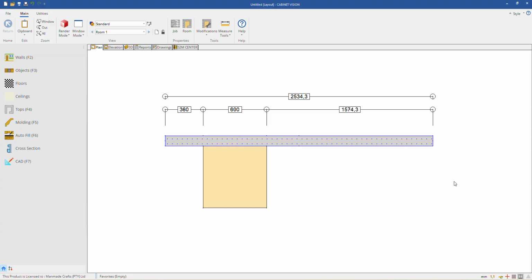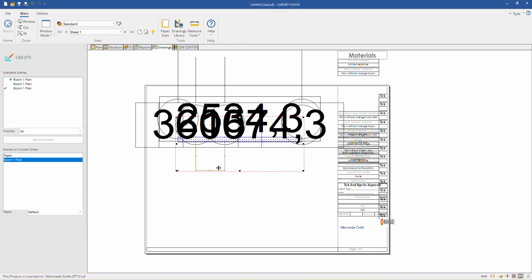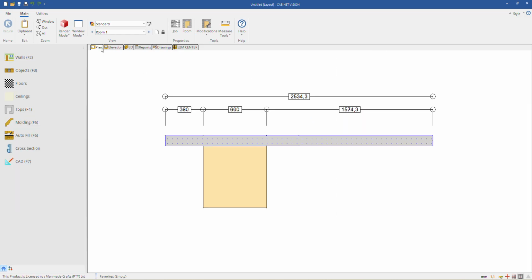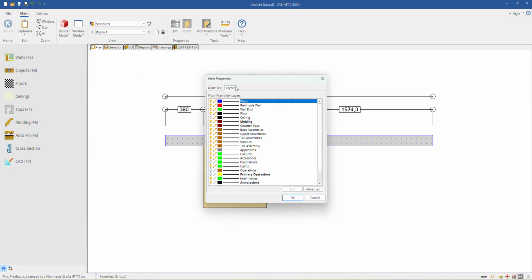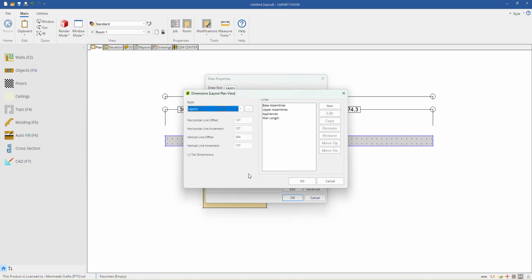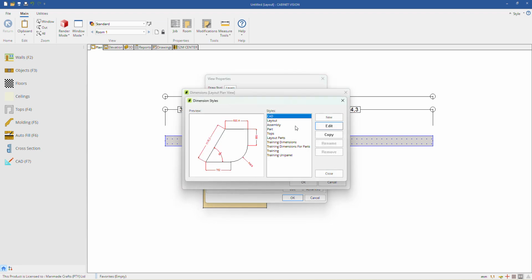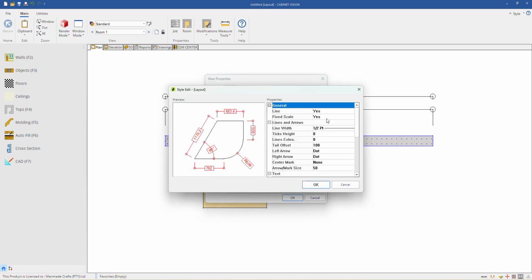So we fixed the font size instead of allowing it to resize according to the scale. Wherever there is a fixed scale option, always say no, even if it sounds like a good idea to set it to yes.